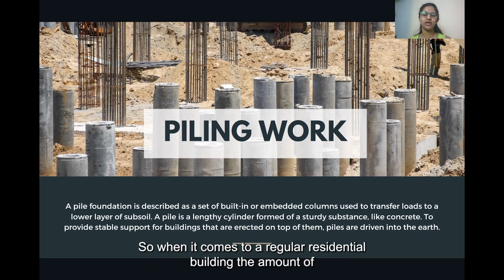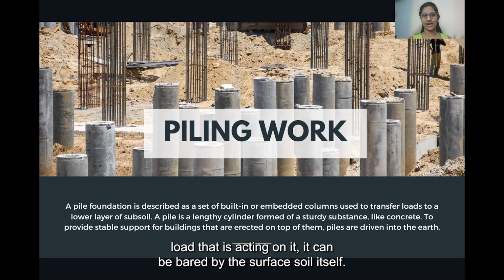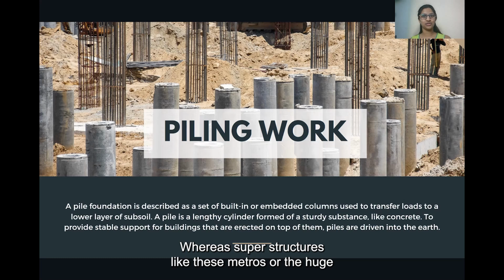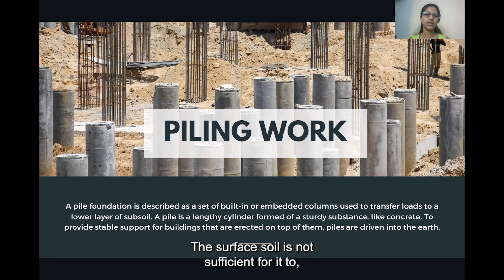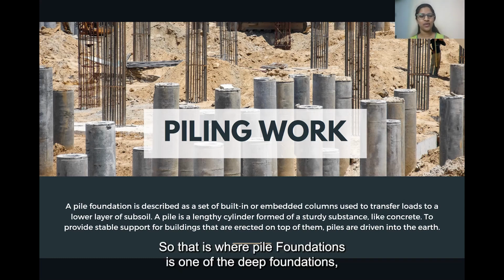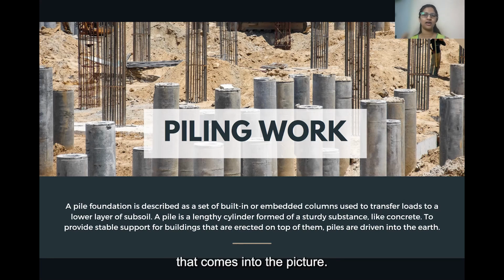When it comes to a regular residential building, the load acting on it can be borne by the surface soil itself. Whereas for superstructures like metros or huge bridges, deep foundations would be required, as the surface soil is not sufficient to carry or transfer that load to the ground. That is where pile foundations, one of the deep foundation types, come into the picture.